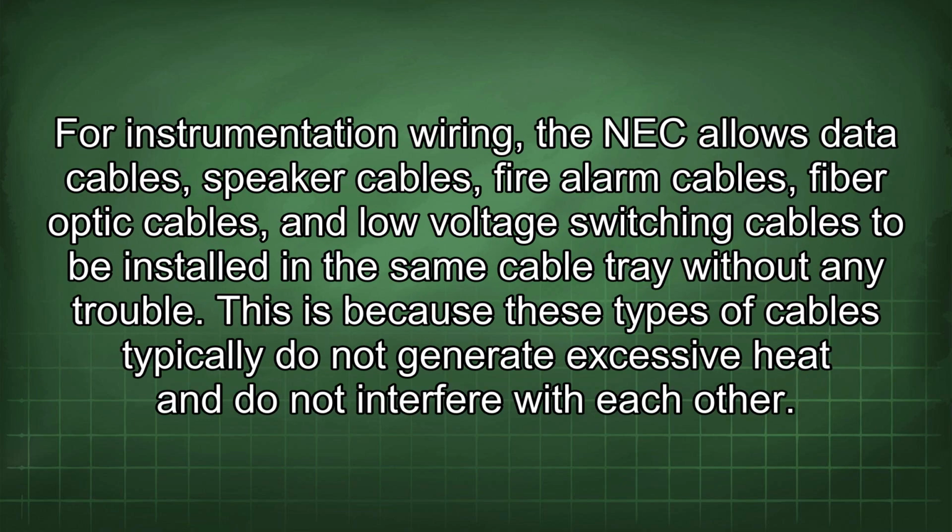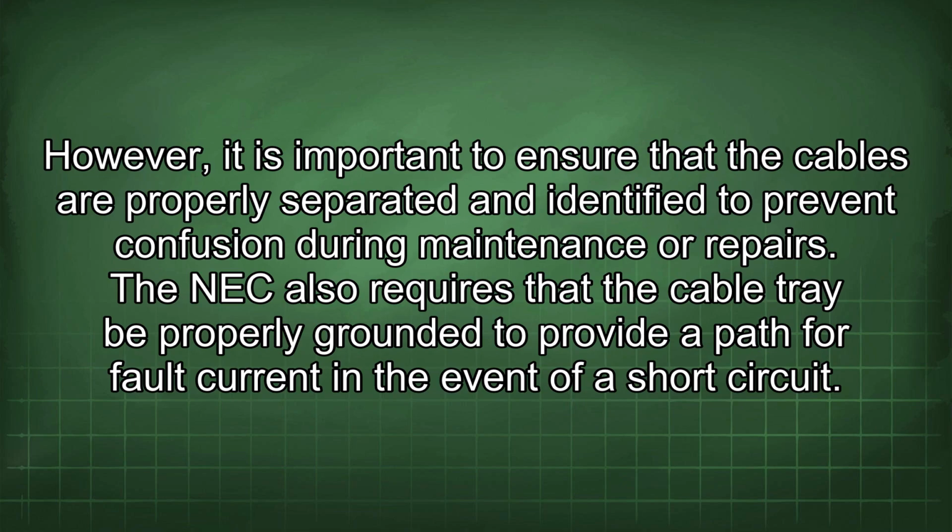For instrumentation wiring, the NEC allows data cables, speaker cables, fire alarm cables, fiber optic cables, and low voltage switching cables to be installed in the same cable tray without any trouble. This is because these types of cables typically do not generate excessive heat and do not interfere with each other. However, it is important to ensure that the cables are properly separated and identified to prevent confusion during maintenance or repairs.